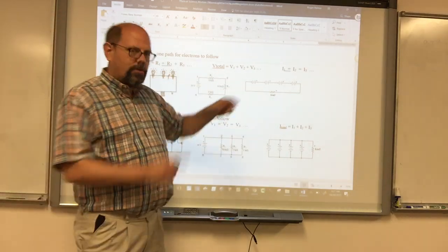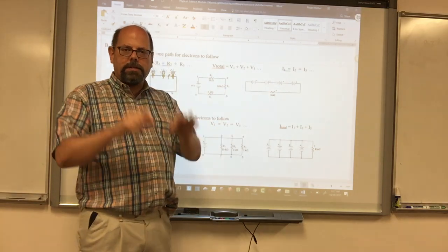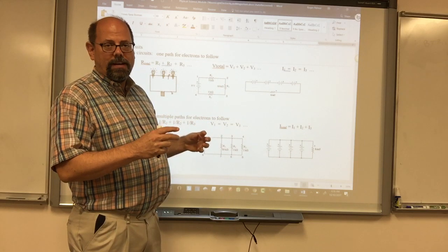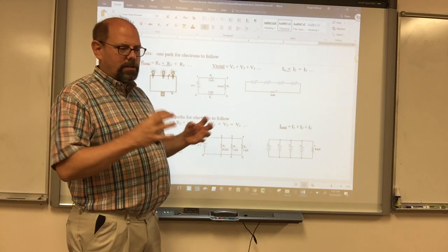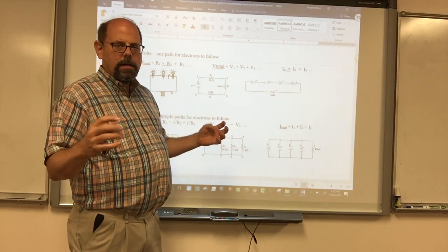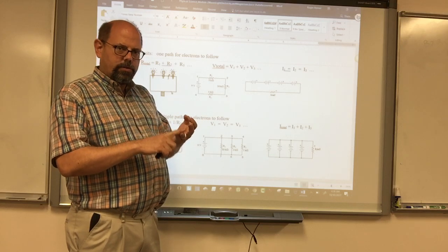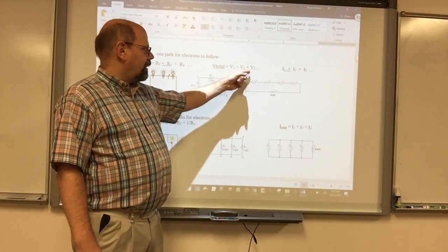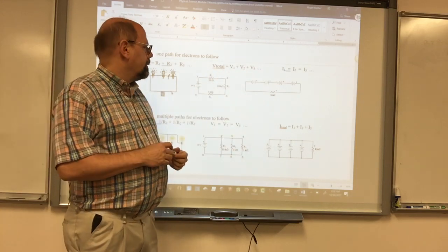What's also true is voltages. If you take a bunch of batteries and hook them up in a row, from the plus to the minus, plus to the minus, they're additive as well. If you put three 1.5 volt cells together head to tail, you have 1.5 plus another is 3 volts, then 4.5 volts. So by putting them head to tail, you get bigger and bigger voltage.